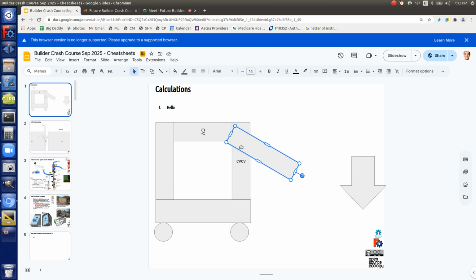So when we calculate 7,000 pounds, say your loader's hydraulics went out and it just dropped with 7,000 pounds on it, you can easily count that the impact there was like 70,000, 10x. Because it's basically like you hit the ground and it gave in a little bit, but it stopped pretty short. Impacts are typically counted as 10x. But yes, in principle, if we use that quarter-inch 4x4 tubing, it would actually still hold, because we just said 200,000 pounds. So you might actually survive that accident without any damage.